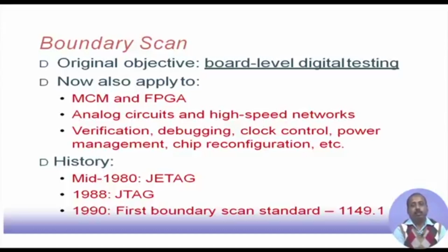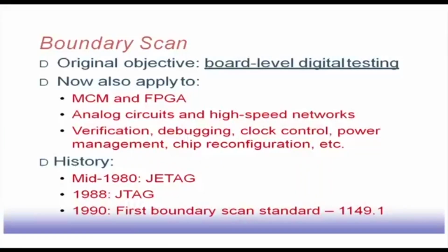In an FPGA, the design is very modular, because we have a similar set of configurable logic blocks distributed throughout the chip. If you want to test each of them, then we have to again send some test pattern to each of these CLBs, and that can be done using some chain architecture, so that the test patterns can be fed to the individual inputs of the CLBs. That way FPGAs also have boundary scan.